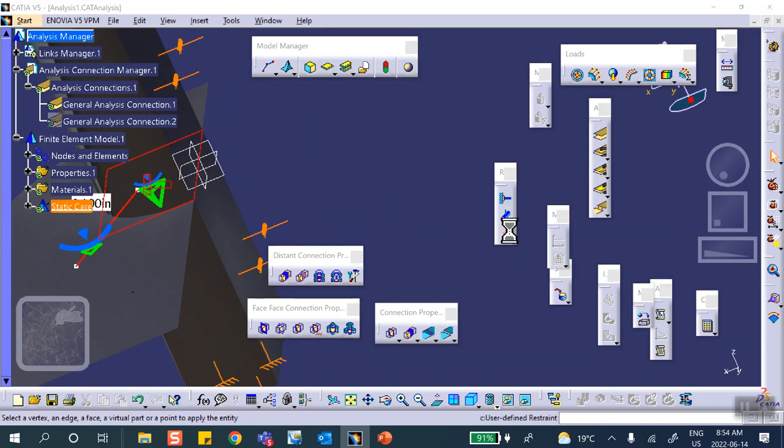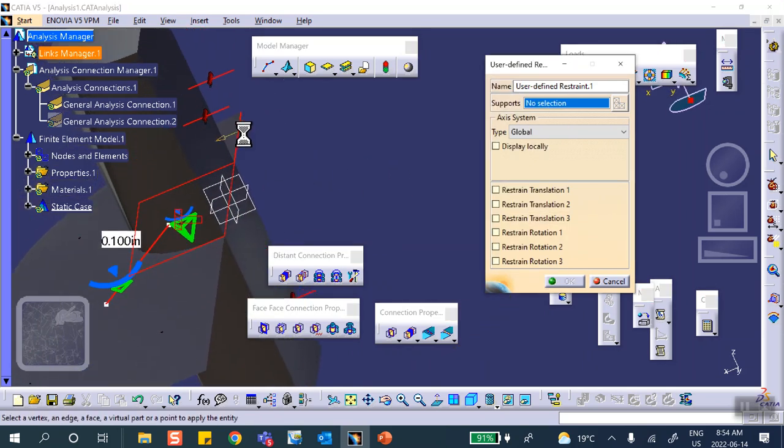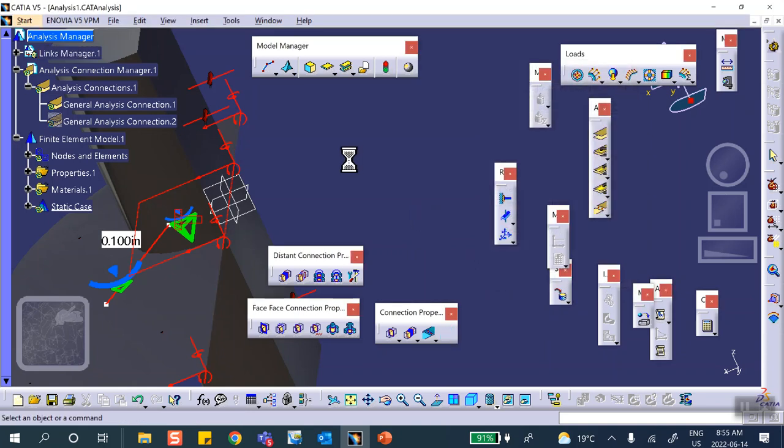Okay, so we do surface defined restraint, uncheck all of these. That's a good strategy to uncheck them. This edge and that edge, these are on the plane of symmetry, YZ plane of symmetry. As soon as I say YZ plane of symmetry, no X. No X. And once you get the translation, these are exactly the opposite. Notice that that circle, half a circle, is not on the plane of symmetry, obviously. Okay? It's just these two edges that are on the plane of symmetry. And we say, okay, let's save everything